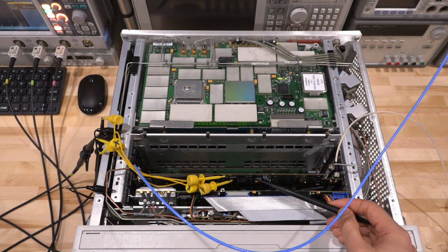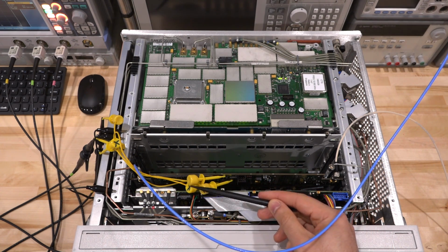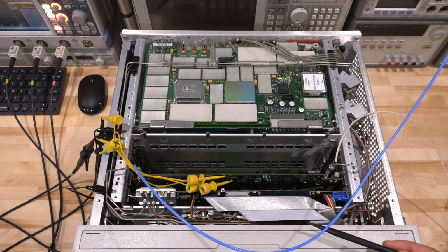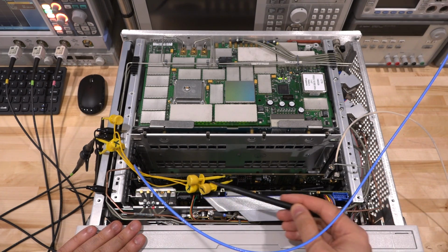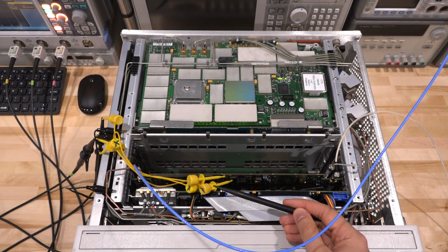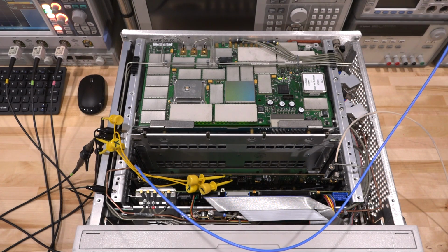And then the PLL, of course, has to follow that so we can monitor and identify what each of these pins actually are. This is a nice way of doing it because we don't rely on the instrument. We control the reference. We can monitor everything and find out which ports of the VCO are FM and which ports are for tuning. So that should be pretty easy. So this is completely out of the picture this way. I should really terminate this, but anyway, it's now left floating.